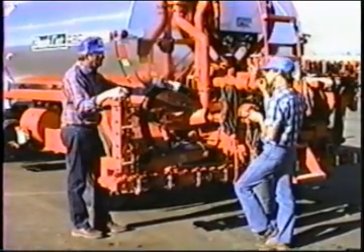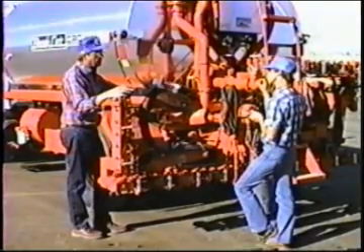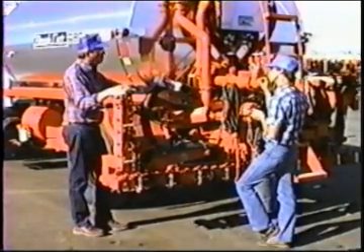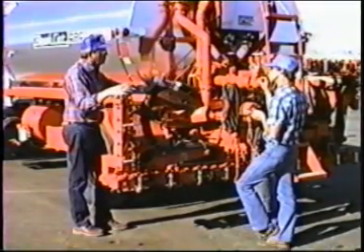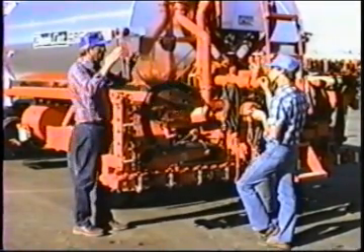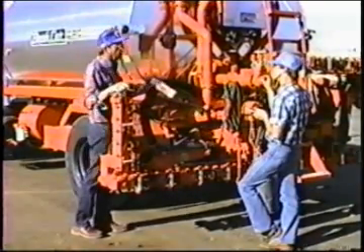It'll fan just fine right down to 2 pounds, and as long as you're paying attention and watching the spray, you can go down that slow. If you go any slower, then you don't have any pressure and the fan will turn to a dribble, and then you create streaking on the road.